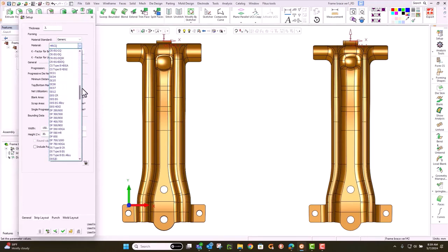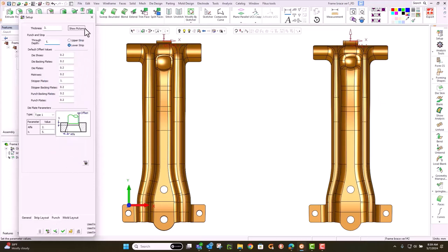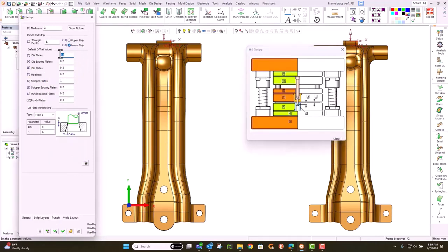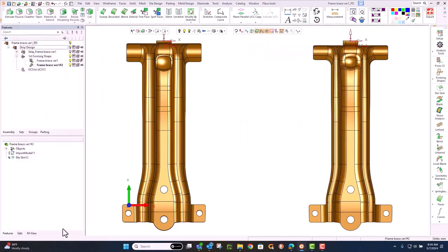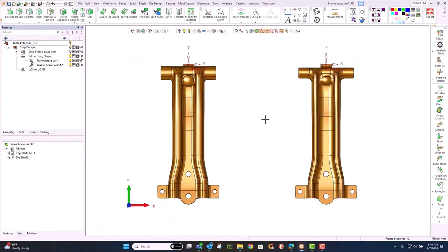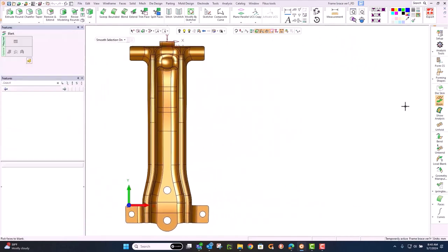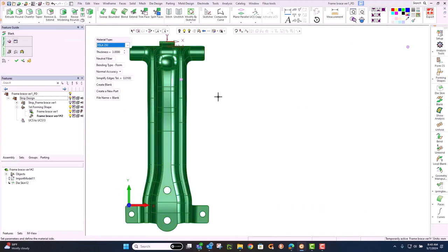And then we set up exactly what we want our clearances to be. So the diagram shows you we're putting in the clearances between the punch and die, how much per each position or plate of that die, what configuration of punch and die do we want. This is now all saved in the setup, and more information, of course, is gathered as we go further along the process, so that with each time we need to form a punch and die, we have the information readily available. Now with this position in mind, we're going to do a crash form, basically an overall quick blank.